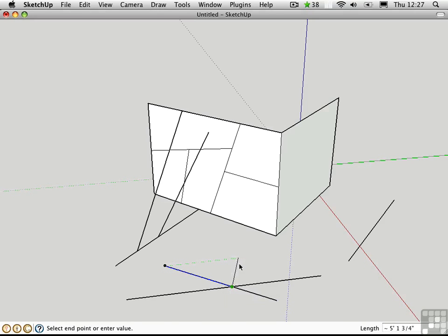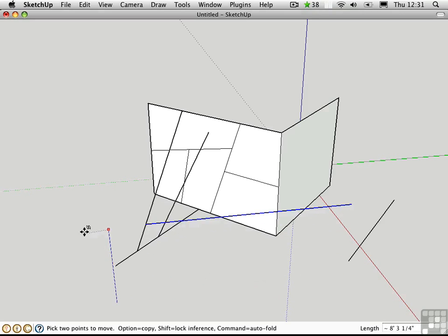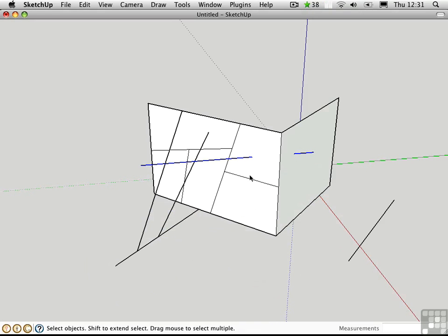You'll see an intersection when a line penetrates through a surface out of plane at an angle. For example, I'll take this line segment and I'll move it over, I'll move it up, and position it just so it penetrates through this surface. Now if I draw a line, I'll get an intersection point, which is indicated by a red X. This is the point where the line just touches the surface. I can now snap to it and draw new lines to it.